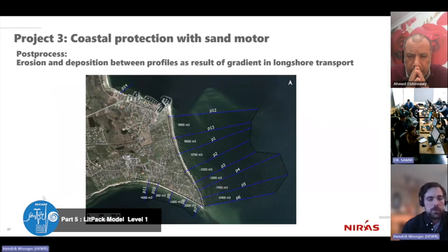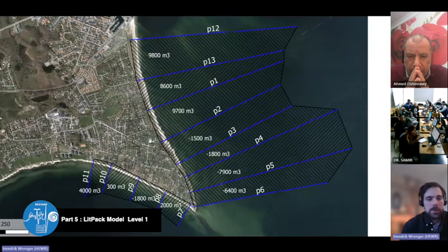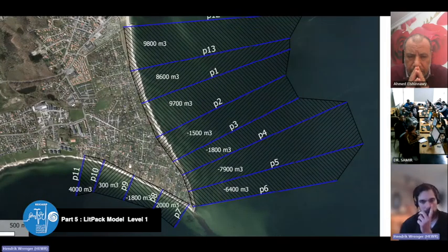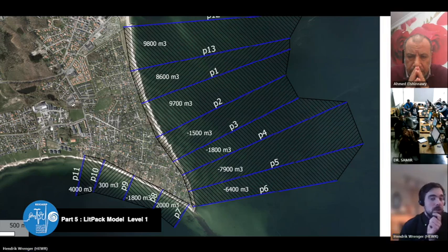Yeah, I can try to go into that a little bit more. The one was around the headland. It cannot be modeled around the headland, because the model formulation of the coastline evolution assumes a baseline and a more or less parallel shoreline and contours with that baseline.